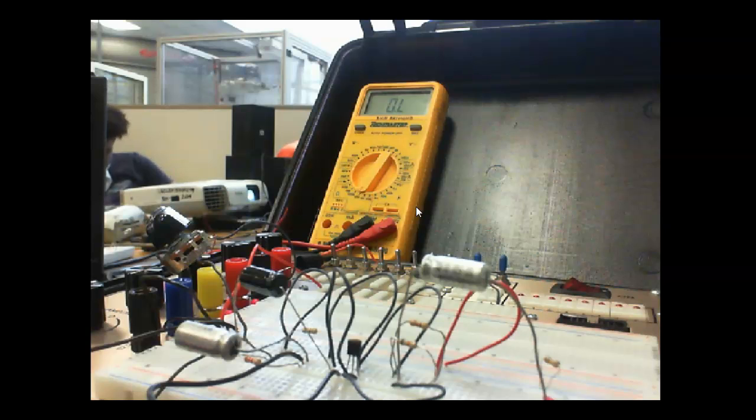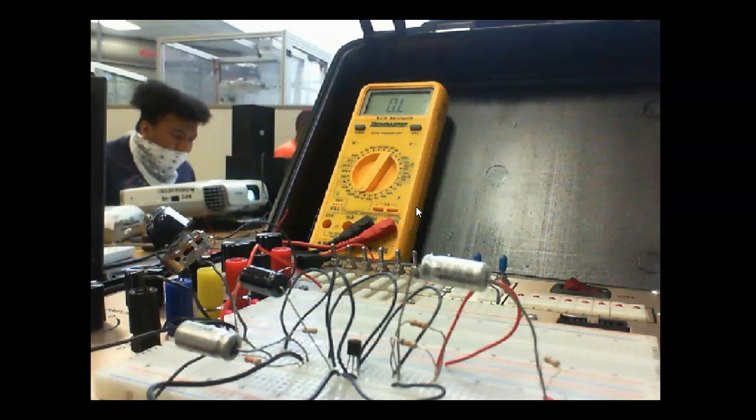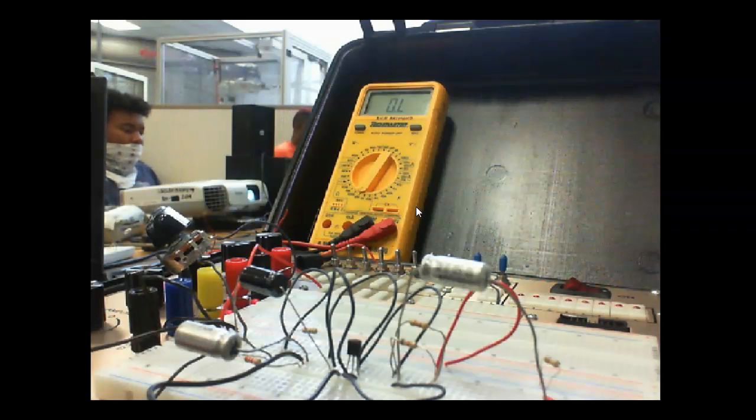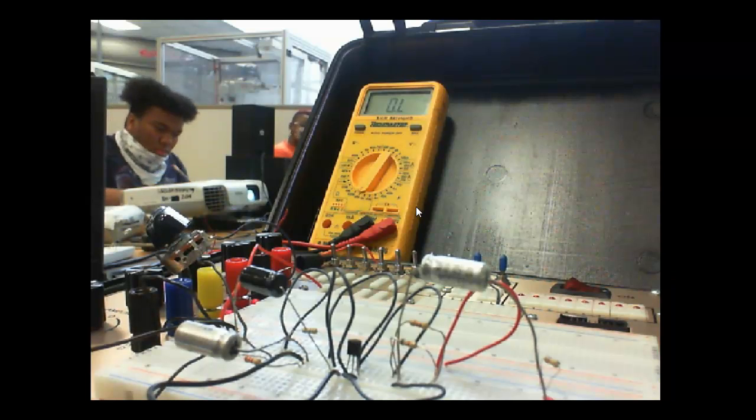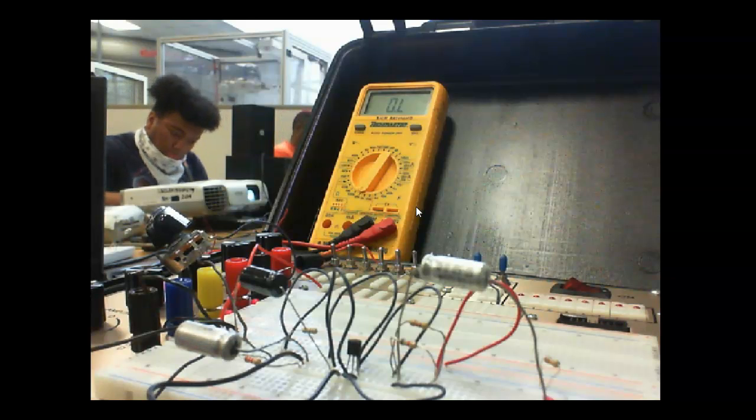So it wants us to remove C2 from the circuit. So we're going to simulate an open C2, right? Isn't that step 8? Of course, we know that the input and output are 180 degrees out of phase, right? That's number 7. Number 8 says remove C2 from the circuit, measure the AC signal at the transistor's base. So we're going to remove C2. What's going to happen when we remove C2? Gain's going to drop way down, right? So if the gain drops way down, that's a good indication that we might have a problem with C2.